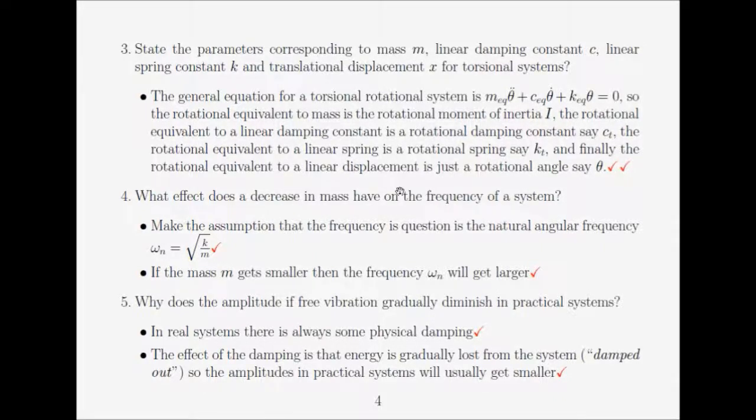Physically, let's say there's a mass, a spring, and a damper, and the mass has some sort of motion. It has a kinetic energy, a half m v squared. There's a potential energy, a half k x squared, if k is a spring constant, and there is some damping energy, typically a half c x dot squared.